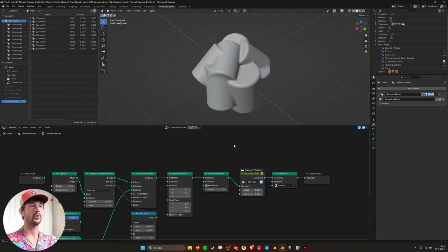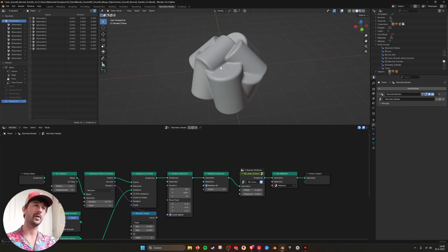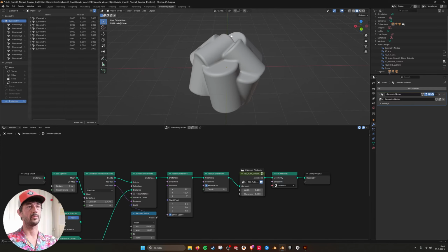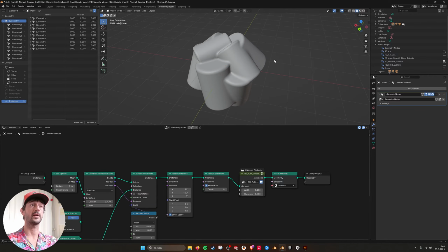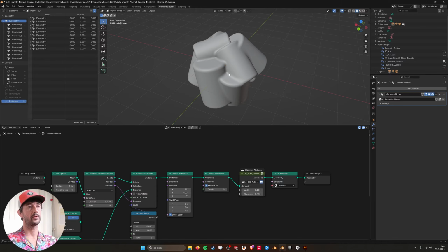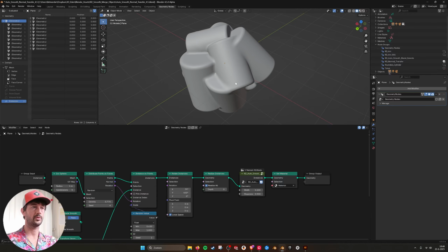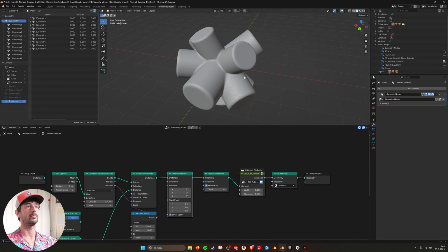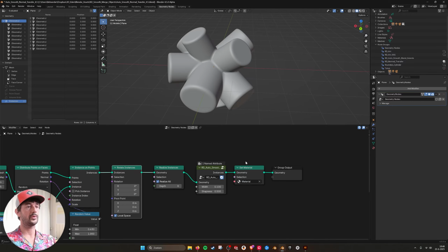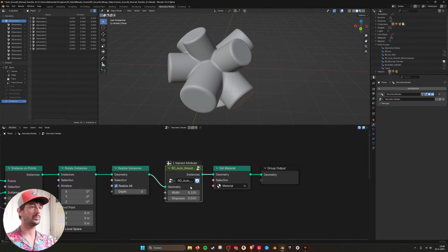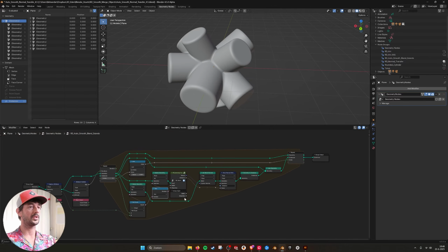And if you would do this with a remesh modifier or make a volume from this mesh and then back into a mesh and blur the position, that's also a method to do it. This would become really heavy, but doing it this way with just the normals, you get a fine result for most renders. So if we go into the node group that I made, here you can see that I'm using